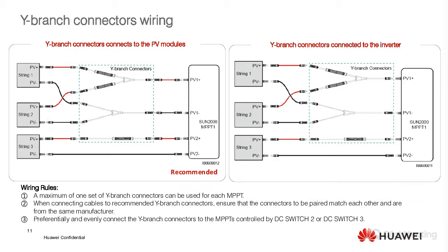You are then going to be able to connect 3 strings. So there will be a Y connector utilized for the single input, and the third input onto that inverter will also require fuse protection because that is a bus bar internally, and that could affect the inverter in terms of damaging the inverter if that inline fuse isn't incorporated within that MPPT.